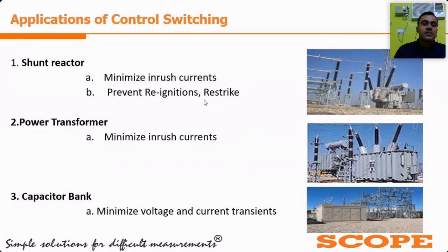Due to this inrush current, at different substations we have seen tripping at the time of ICT first closing or re-energization. To prevent this, we use the CSD relay, and with our point-on-wave switching, we have minimized this inrush current up to 0.002 pu, which we will see in our next slide.